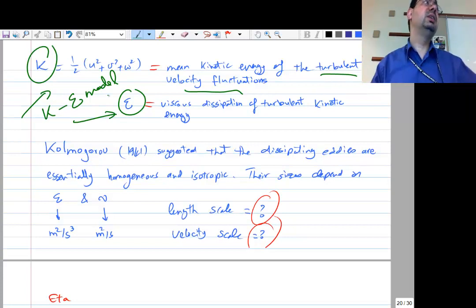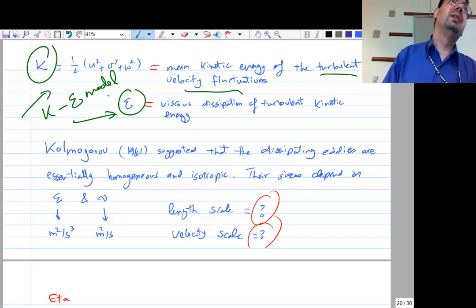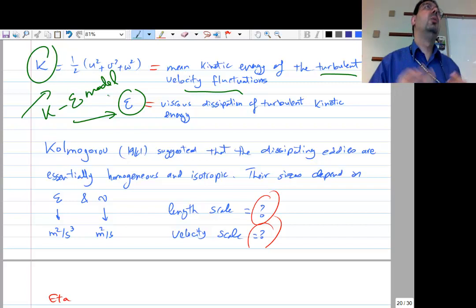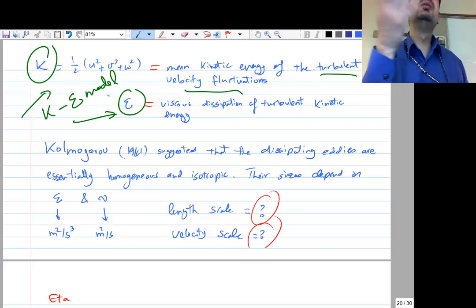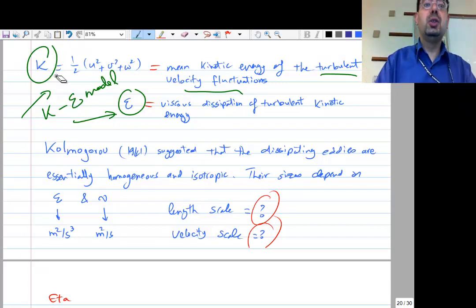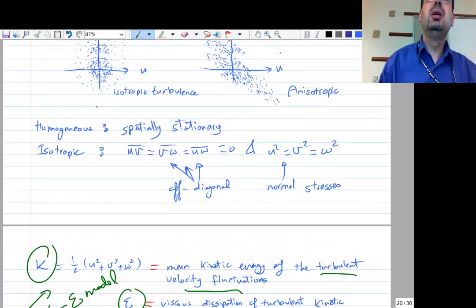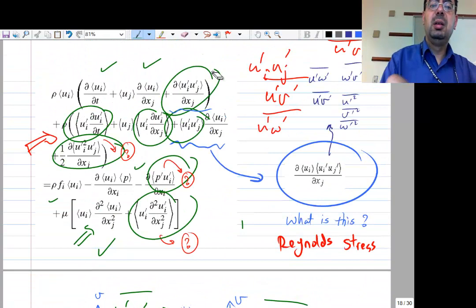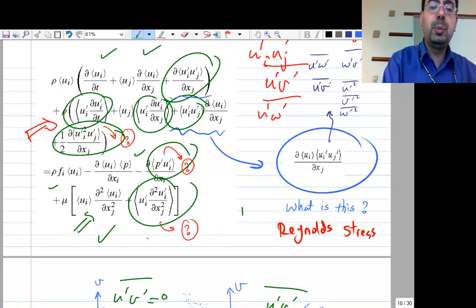It's interesting how these equations are written, because it's not really physical. It's kind of a mathematical equation. You are trying to write an equation that describes what happens to those three fluctuations. Solving this K and epsilon equation will supply those terms. If we don't have values for those terms, we have something called the closure problem in fluid mechanics.